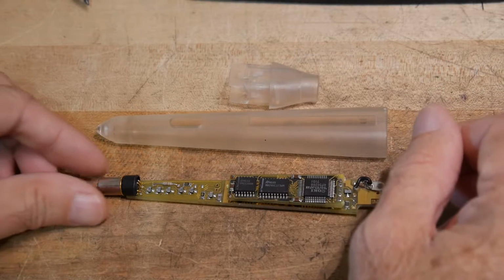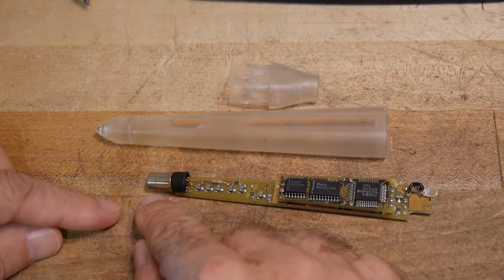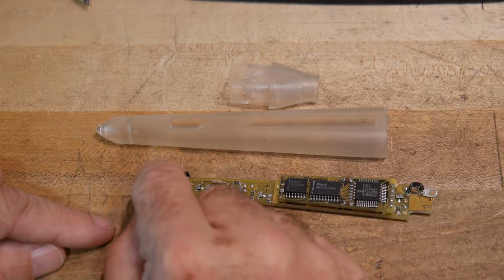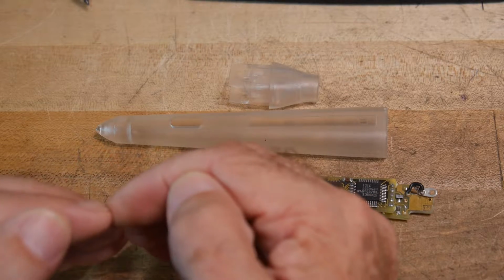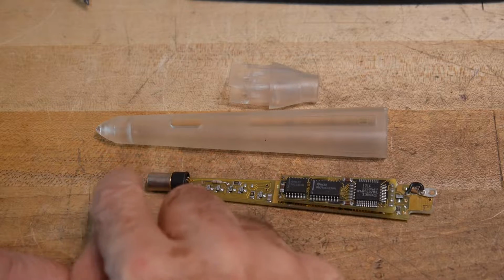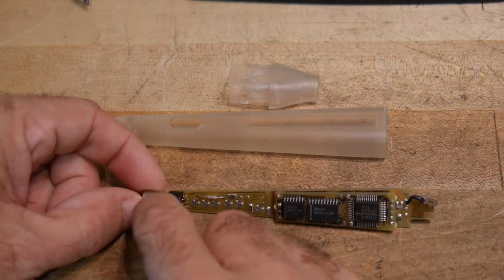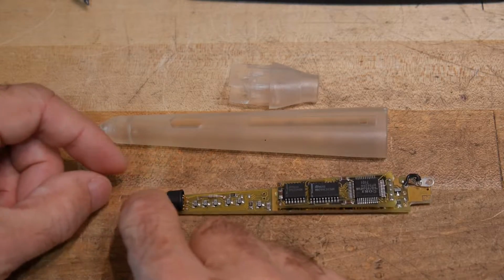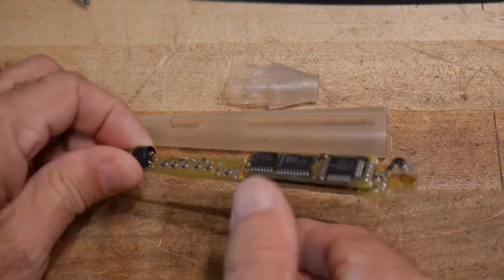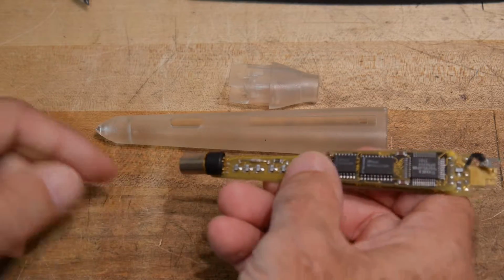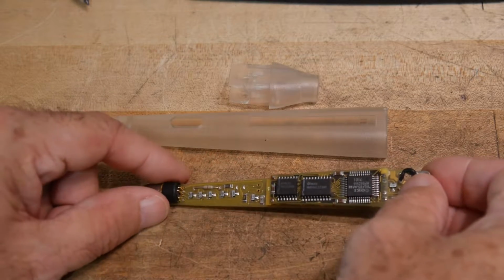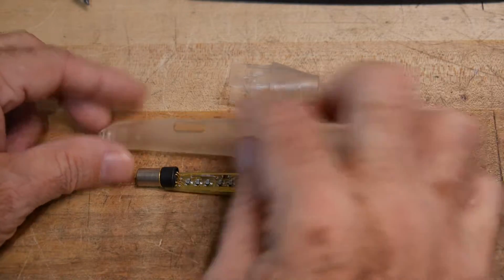First of all, there's an interesting optics inside this can here. This is the place where we have an emitter and detector and two bifurcated lenses. The light goes out to a point and then gets sent back in to a point. So all of the magic of the optics happens inside this can. Some of the barcode readers just had a hole drilled into the case, and you would scan that. This particular one was a sealed unit.